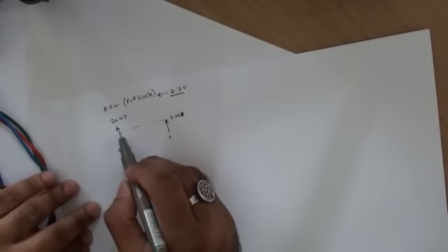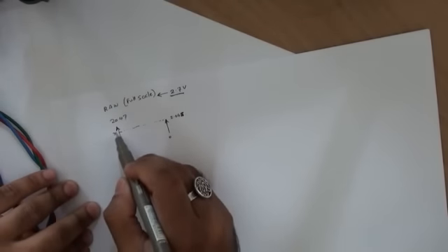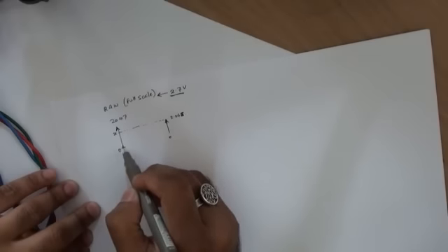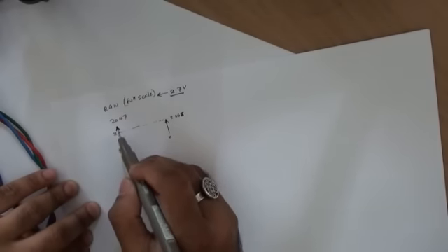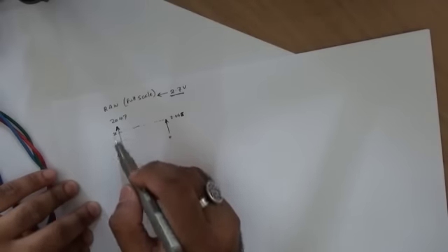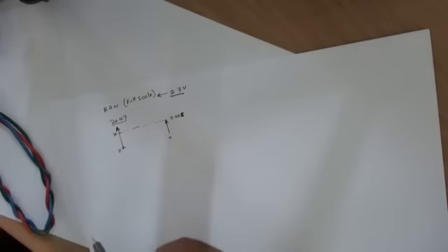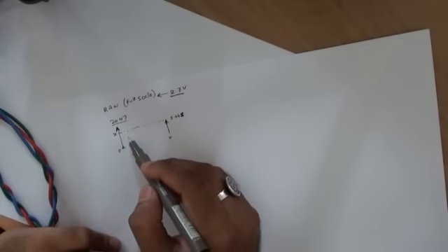Now, once you know an analog representation from 0 to X raw value, you can easily back calculate the full scale value that you would expect to see at that raw value level 2047. You can then use the same scale to calculate the shunt current level.